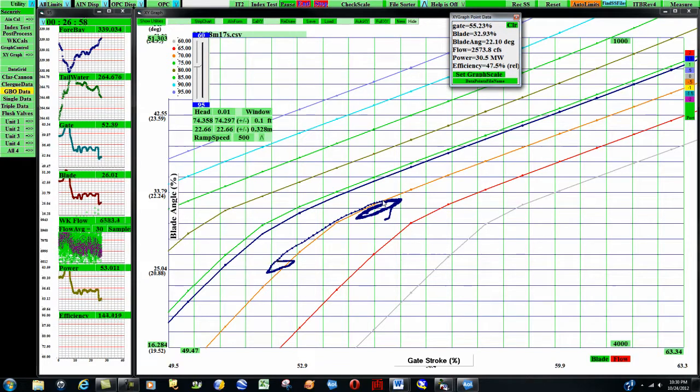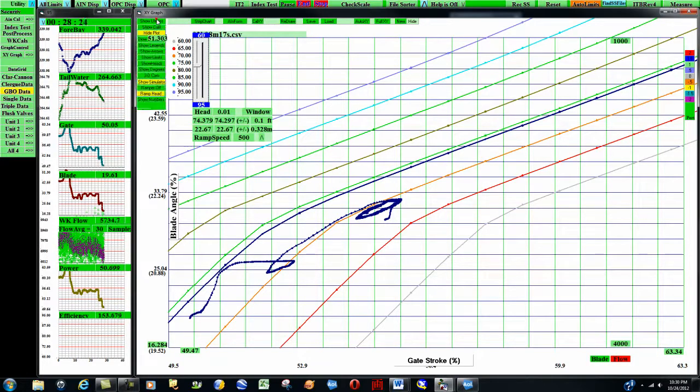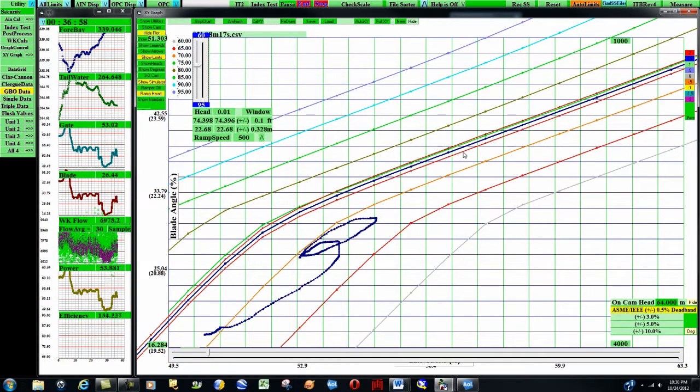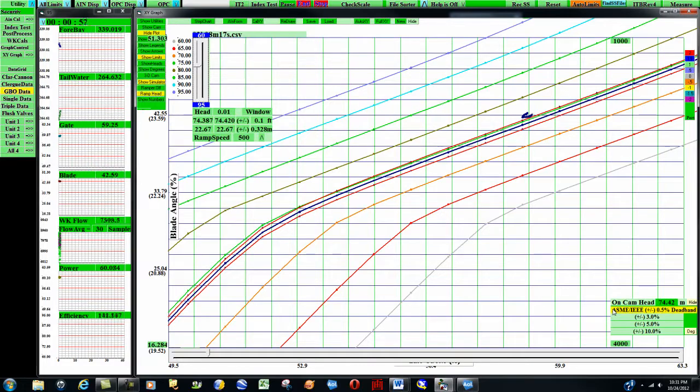Steady-state positioning accuracy and dynamic performance for hydroelectric turbine control systems are defined and quantified using methods and procedures prescribed by the American Society of Mechanical Engineers, or ASME, in PTC 29, and limits are established by the Institute of Electrical and Electronics Engineers, or IEEE, in STD 125. Of interest from these are the measurement methods and limits for deadband and response time. The specified limit for deadband is 1%, or plus or minus 0.5%, and the response time is less than 0.2 seconds.